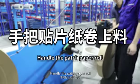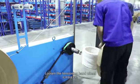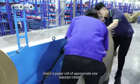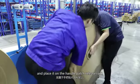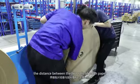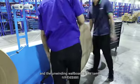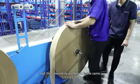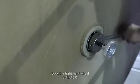Handle patch paper roll setting. Loosen the tension hand wheel. Select a paper roll of appropriate size and place it on the handle patch release rack. Adjust the position of the paper roll. The distance between the two rolls of the patch paper and the unwinding wall border should align with the center line of the handle forming part. Lock the tension hand wheel.